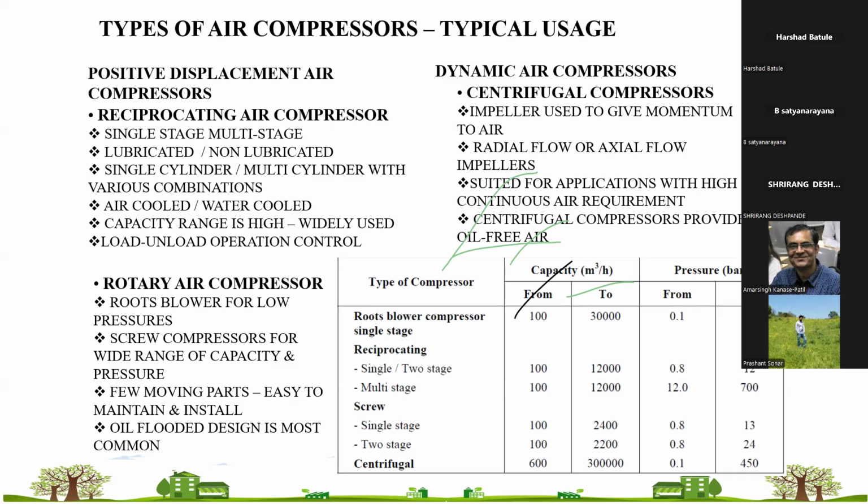I will give the specific pressure requirements of those CNCs and VMCs, and then general air cleaning will require 3 to 4 bar. Another term for that particular application is the air quantity requirement, which is called free air delivery, more commonly used for compressors.